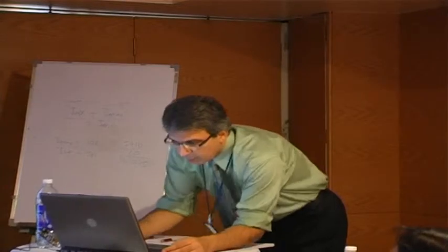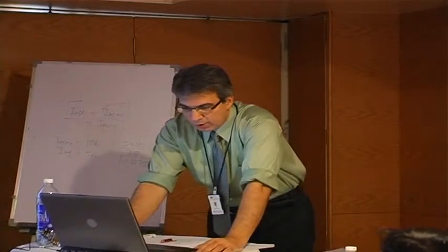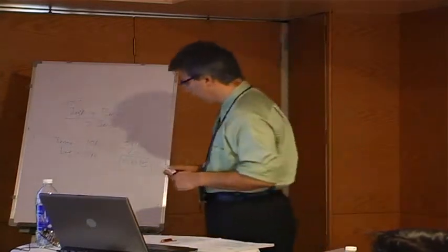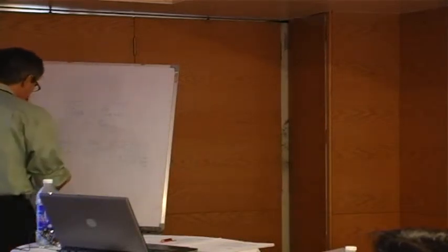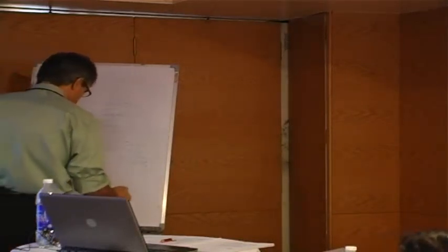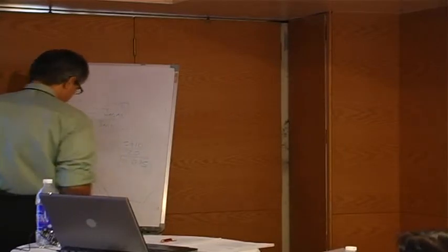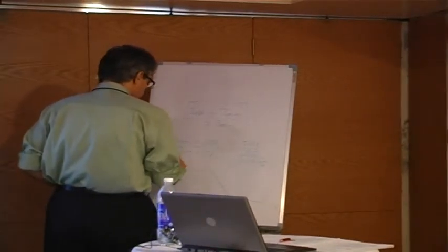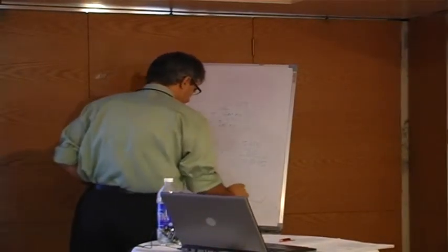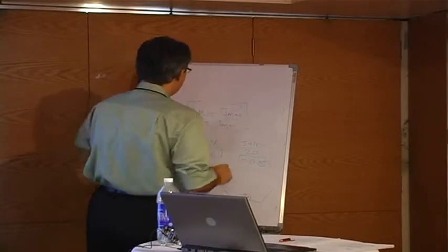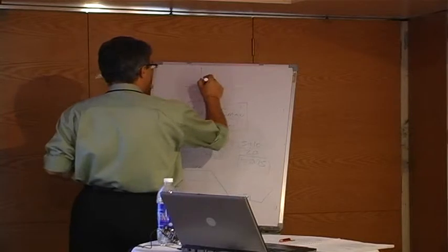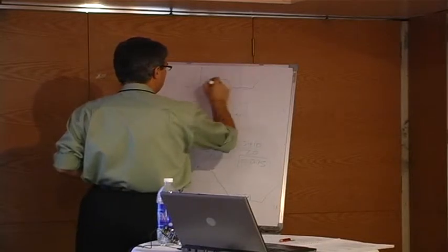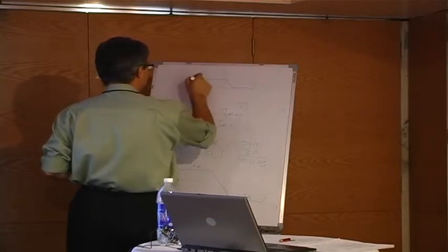Okay, so here the current we are asking for is trapezoidal in nature, right? So these two waveforms at the bottom essentially generate a current which is like this. And we take that current, and let's say if I reference is 5 amps, this is evaluated as 5 amps and minus 5 amps. And by adding this term, we essentially are shifting this reference to give us a duty cycle command. We can call it DA.